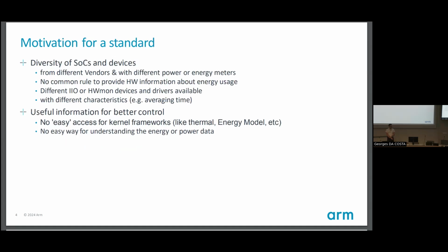And this is the motivation for this new standard. We have actually diversity of SOCs, and we would like to actually standardize something which is kind of a basic thing, which is an energy meter. So because we don't fully control our vendors that can implement different firmware or different drivers, and there are existing interfaces in the kernel, but yeah, the specifics of a particular hardware or a device, this is not reusable easily for something like thermal or power cap, that I will explain a bit later.